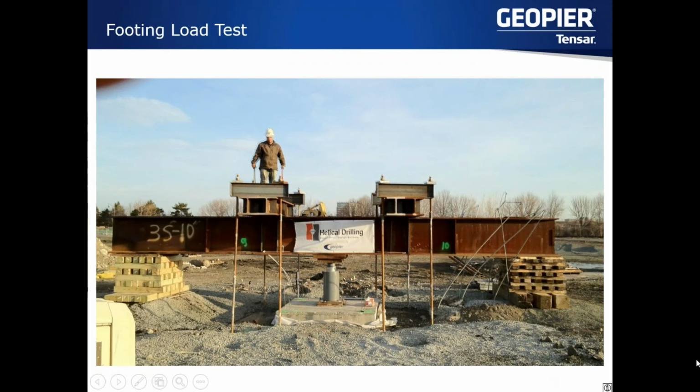One thing we're also able to do is run a full-scale footing load test, and that's what's pictured here. One drawback of a full-scale footing load test is it's about 10 times as expensive, and takes significantly longer to install and to run. What it involves is installing several piers beneath a test footing, whatever it might be, the largest footing on site, a 10 by 10 footing. We'll reinforce it after we install the piers, and then we load that footing to, in some instances, 1.5 or 2 times whatever the design stress is.